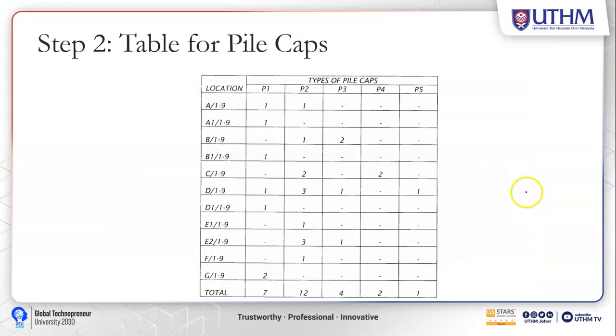Done. And then we need to create this table for pile cap. You need to know the location according to the construction drawing layout for pile cap. So everything needs to be in detail, because if you do like this, it will ease you when you have to recheck all the necessary numbers of piling work.